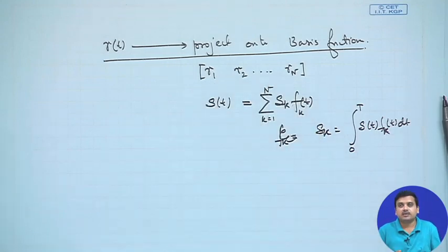When we discussed M-ary FSK, we did say we are calculating the cross correlation function. When calculating the cross correlation function, we did integration of the received signal multiplied by any one of the other signals, and the complex conjugate of it. We wanted to establish that the received signal is orthogonal to all other signals than that particular component on which it has been sent.